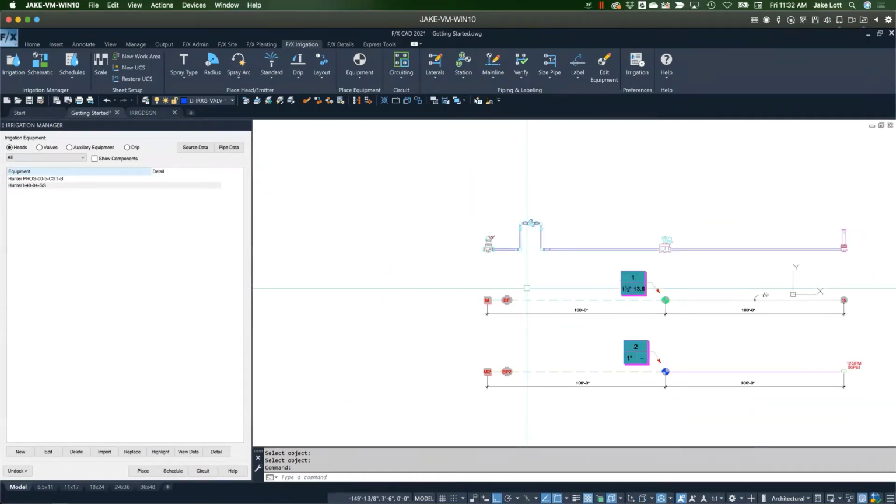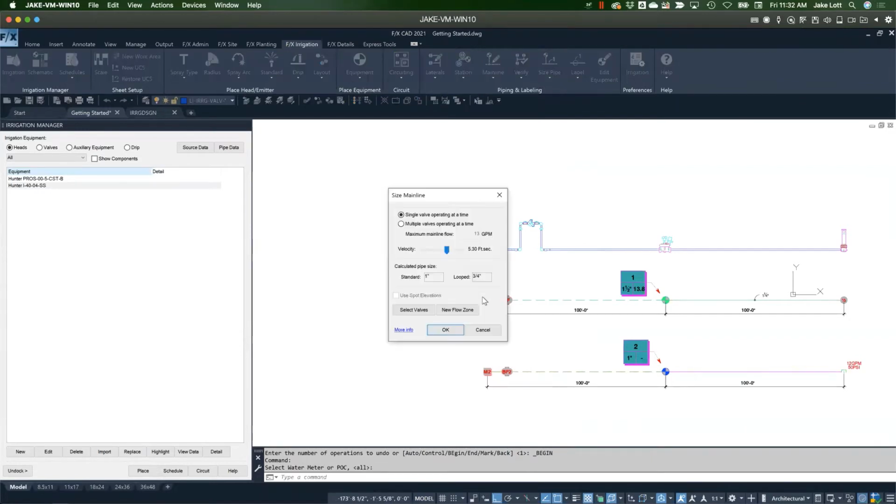So now what we've got is, obviously, working our way back through from the valve to the main line. So we need to size that main line and basically see how this cross-checks with, or compares with, what we have available. We obviously have one valve, so that's what I'm going to do. A very similar theory is behind this when sizing, which is velocity.